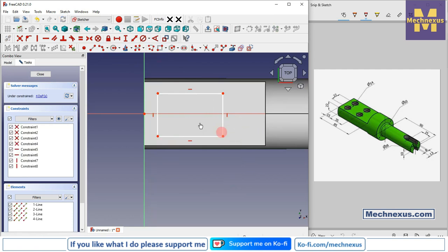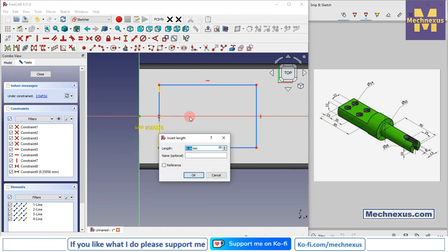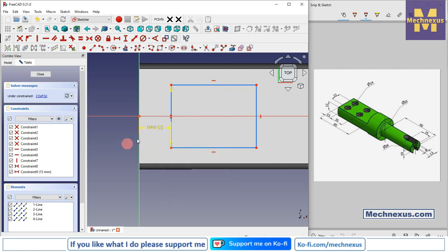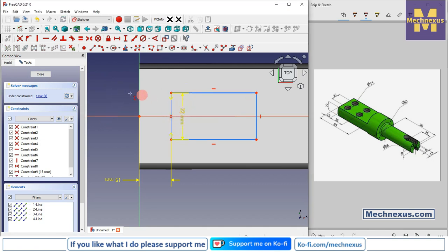and here first thing I will do is create a rectangle and make it construction, and now select the symmetricity and make this 2-point symmetric, and position is of 15 mm. So I will select this point and this point and provide the 15 mm, and this is the 22, and hole to hole is of 35. Select this and provide the horizontal dimension of 35.